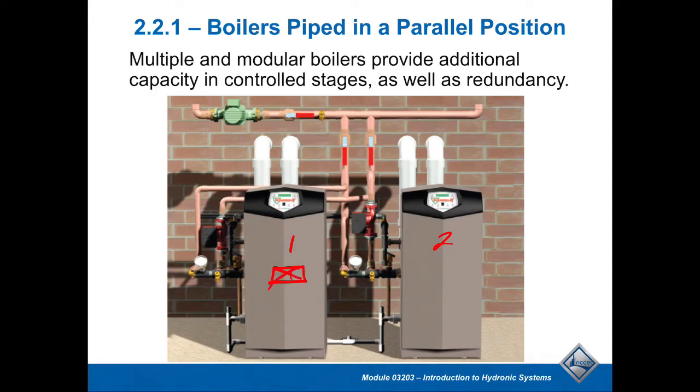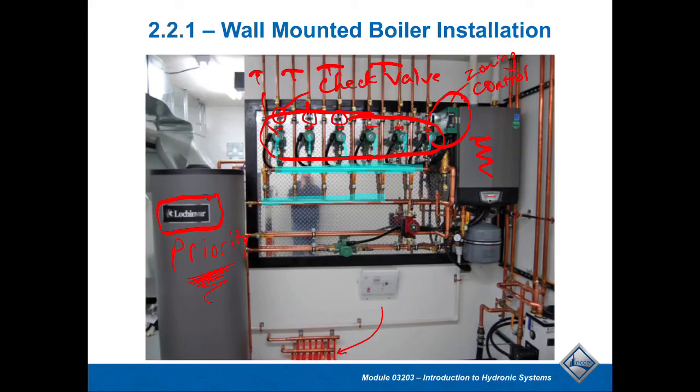The other thing that I want to point out is, you notice how you have boiler number 1 and boiler number 2. We now have built-in redundancy. The beauty of this is, let's say I don't want this boiler running, this one can kick on and provide us some heat, or we can use them both. So there are a lot of advantages there. We can stage it, we can control it that way. It works really well.